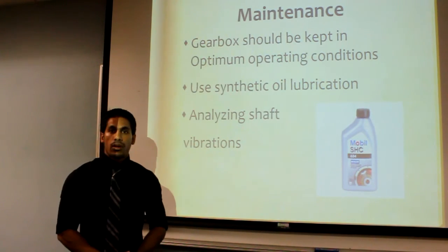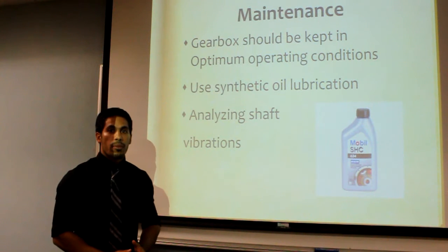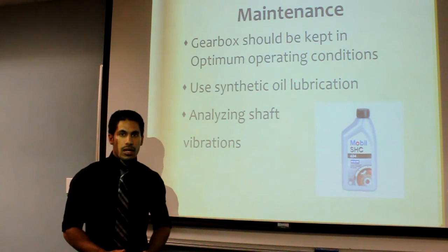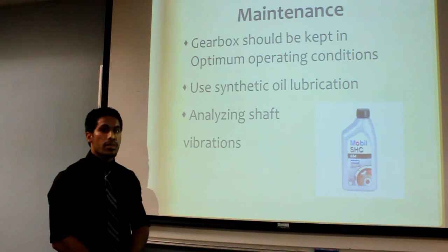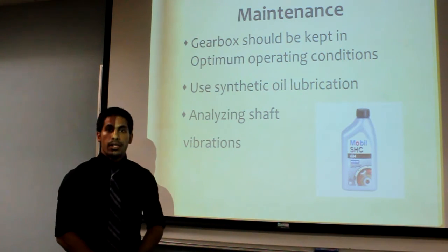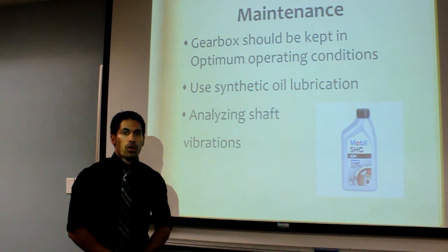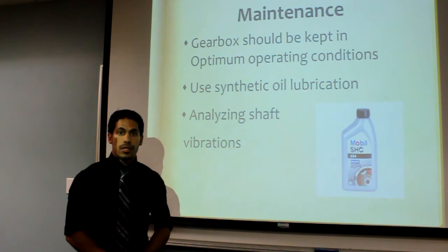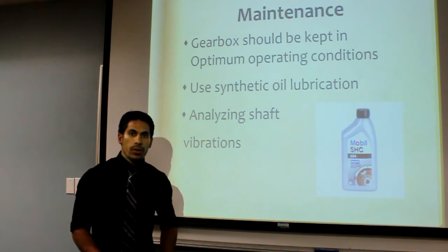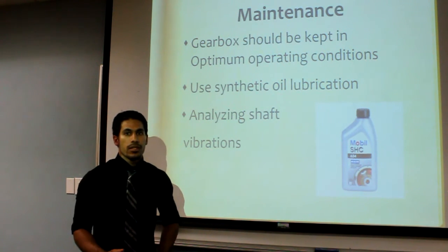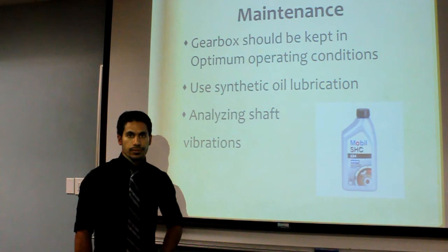For the maintenance, our gearbox should be kept in optimum operating condition so that the facility can operate at its most efficient. One of the most important steps to increase the gearbox life is to keep it properly lubricated. We highly recommend using synthetic lubrication because, due to the vast ambient temperature range, synthetic oil is a great choice because of its high viscosity temperature.